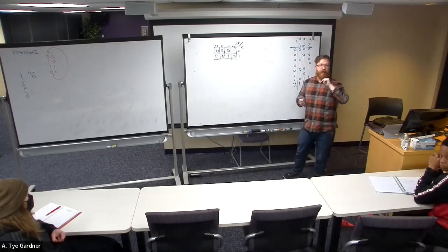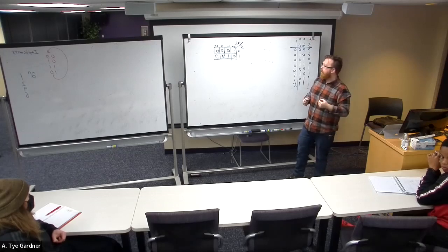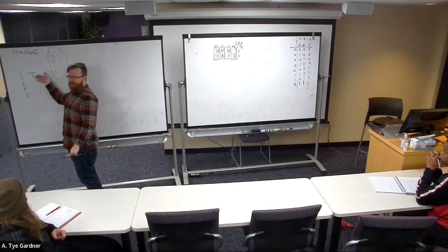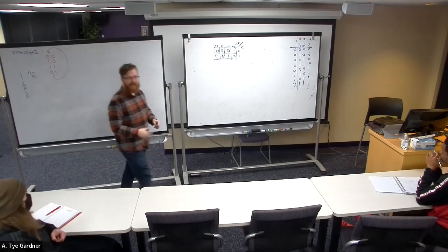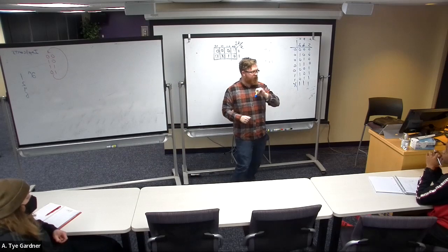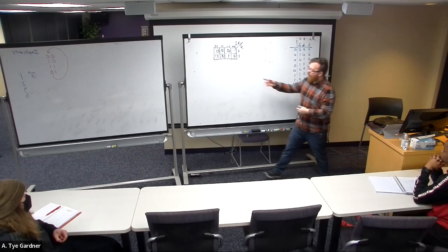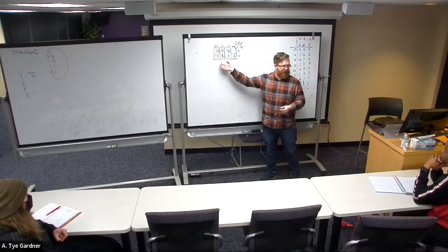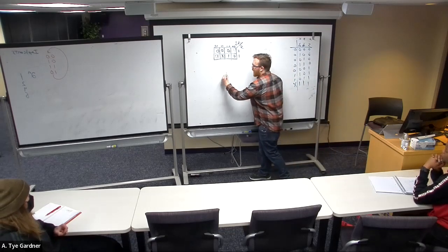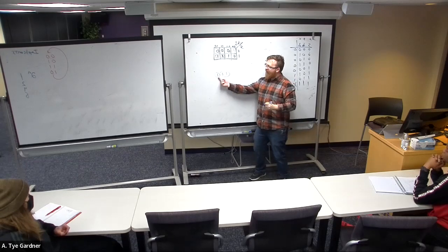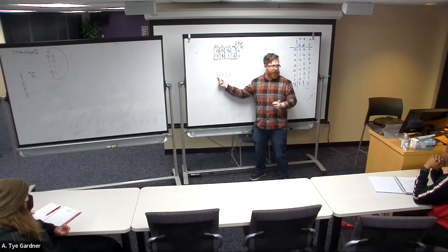So why don't you just have 1 circle for all of them? Because 3 is not a 2 to the n option. If it was a 1, you'd have to circle it. But it turns out if that was a 1, then this is still the minimum expression, because if I can circle a bigger implicant, I must circle the bigger implicant in order to achieve a minimum circuit.